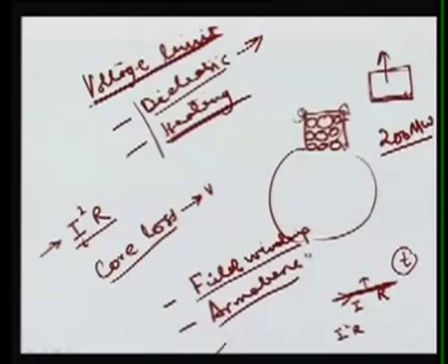So cooling is very important, but once it is decided, we should operate this generator within its capability limits. The various capability limits are your field and armature and end-region heating limits, which I will discuss in the next lecture. Then we will form one zone, which we also call the capability curve, in terms of real and reactive power. We will see how, in terms of real and reactive power, we can draw one zone, and that zone is basically the operating zone, the capability curve of the synchronous alternator, which we will see in the next lecture.